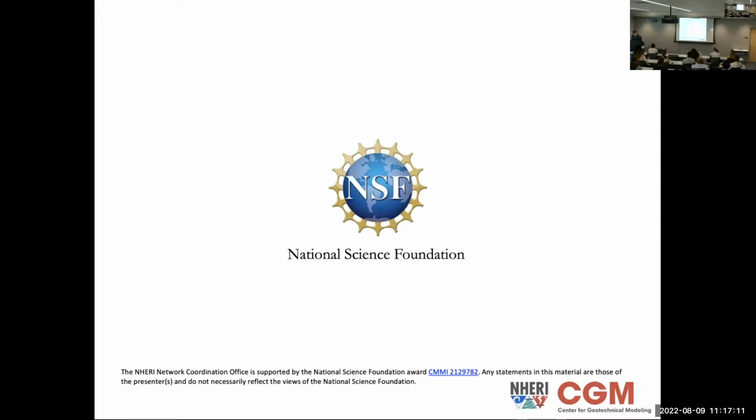So you're saying about the centrifuge that it can scale down things really nicely. Yes. But what about the actual failure itself? Is that still the same failure that you'd see at the large scale? So the failure itself, because distance is proportional, if it's 3 millimeters, it'd be equivalent to 120 millimeters. It's a little weird sometimes with some of the scaling factors, because it has to do with acceleration. Time is a squared factor in acceleration. So that's why time ends up being squared.